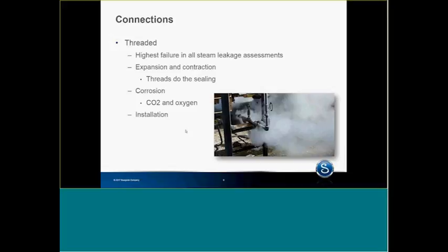If you get into the thread associations and the technology and everything else, we're relying on the thread itself to do the sealing. And yes, I've been through the Teflon tape and the blue sealant. It's not a sealant, it's a lubricant. The thread ends up being the sealing point.